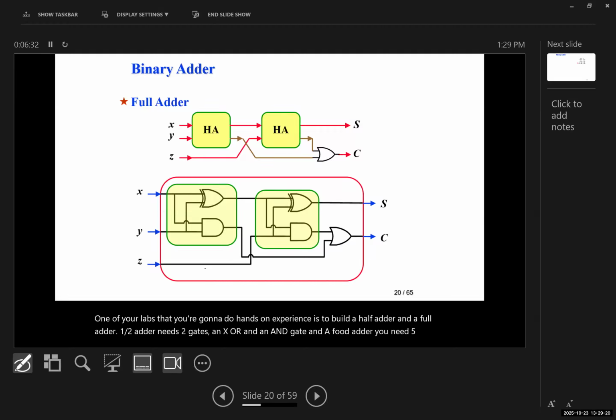So to reduce the carry propagation delay, the first thing that we can do is to employ faster gates. We can have a look ahead carry, which is more complex, but it's faster. We have the carry propagate, where Pi is equal to Ai XOR Bi. We have the carry generate, where Gi is equal to Ai AND Bi. We have the sum, where Si is equal to Pi XOR Ci. We have the carry, where Ci+1 is equal to Gi plus Pi Ci. C0 is our input carry. C1 is going to be G0 plus P0 C0.